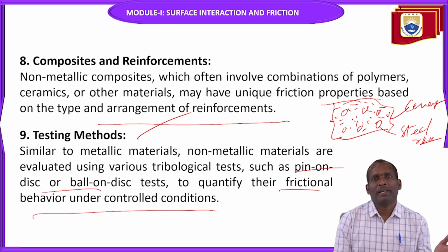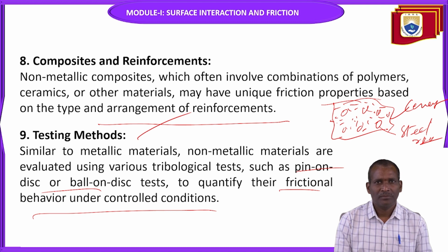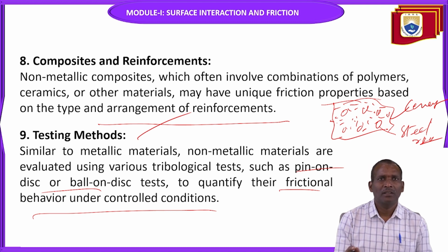So not only metallic materials, you may use non-metallic materials to find out the frictional behavior and wear testing by using a ball-on-disc or pin-on-disc machine under controlled conditions.